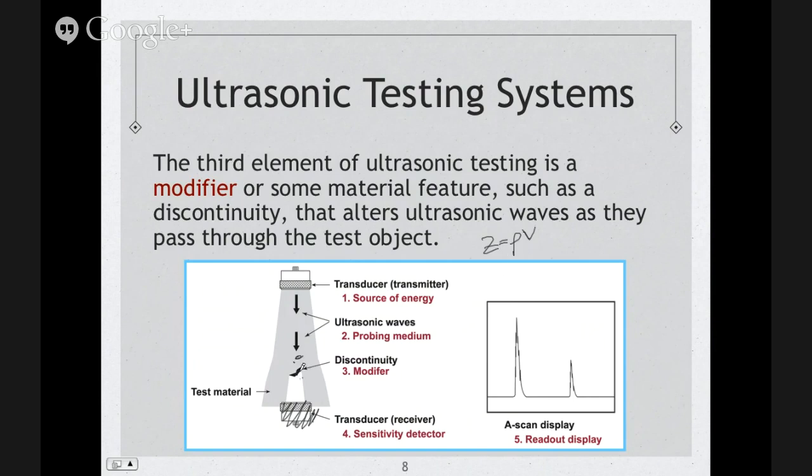And so in air, because the crack is filled with air, and metal, the velocities and the impedance ratios... We had a formula that said the reflection equals impedance 2 minus impedance 1 over impedance 2 plus impedance 1, and if I'm not mistaken, these two were also squared. And that was going to give us our impedance ratio back into our reflection ratio that was going to reflect back.